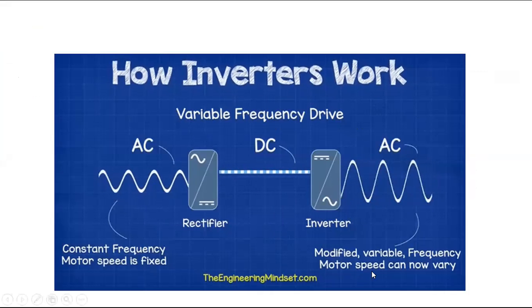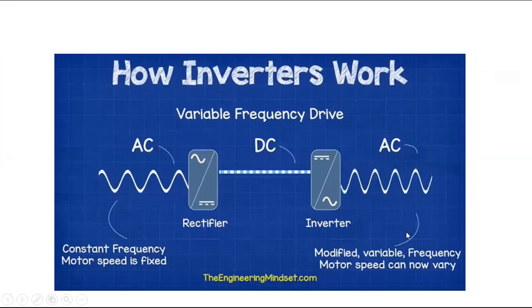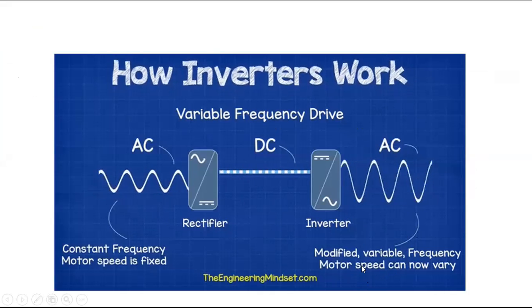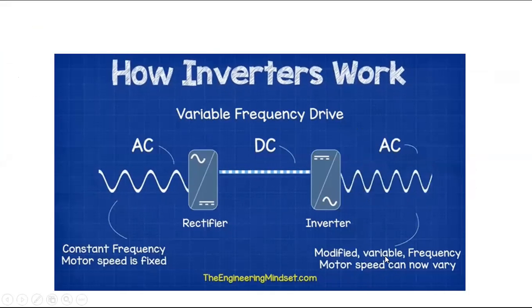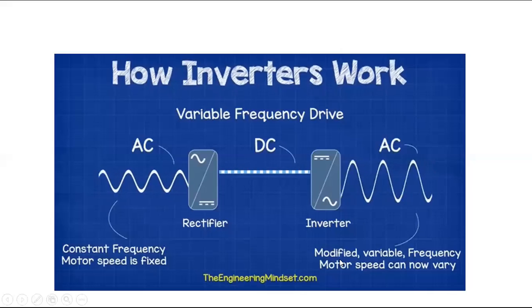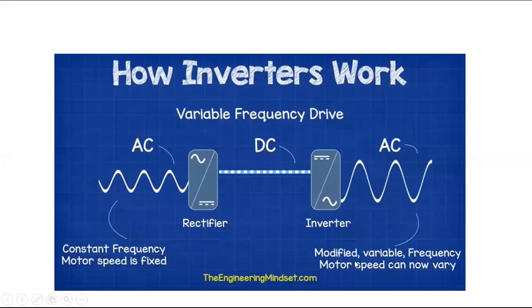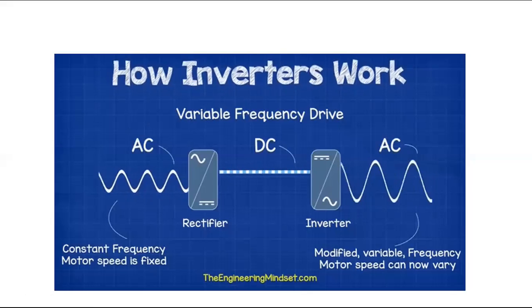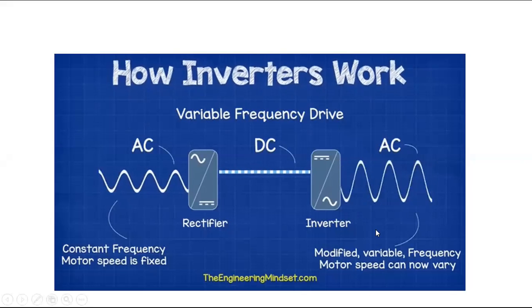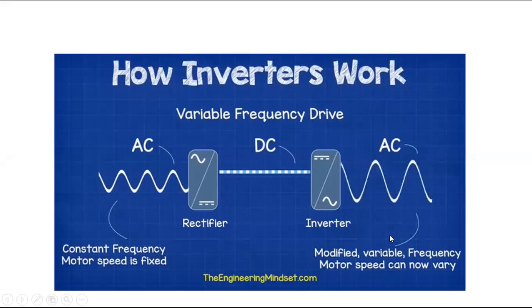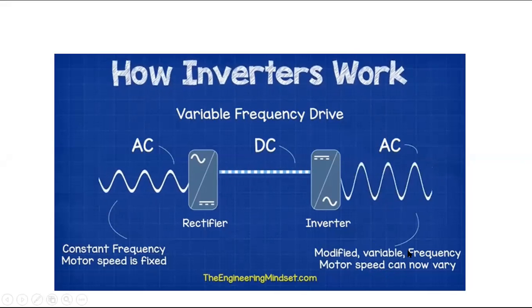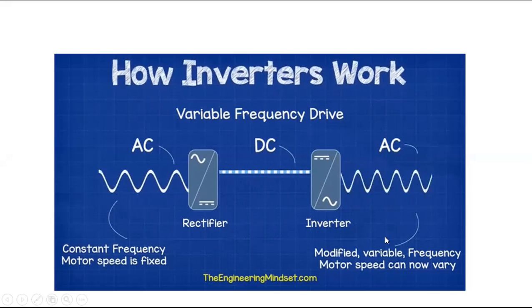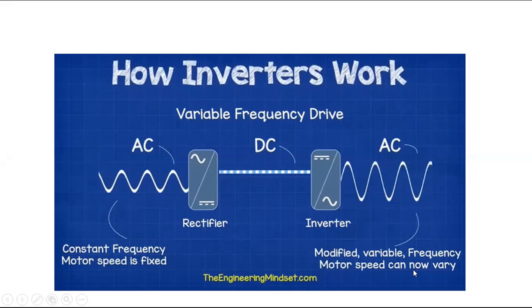Now remember all of you, here you see, I want to control the speed of an AC motor, induction motor, let us say in the industry. In many industries we use the induction motor, let us say the textile industry, the cement industry. So wherever I want to use the induction motor, speed will be controlled by varying the frequency. This is the best method. How to control the speed of the induction motor? Induction motor speed can be controlled by the change in the frequency.